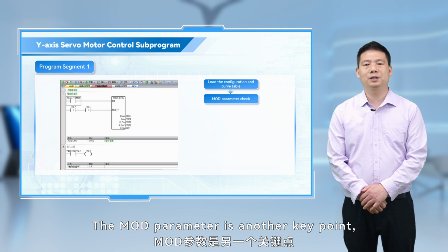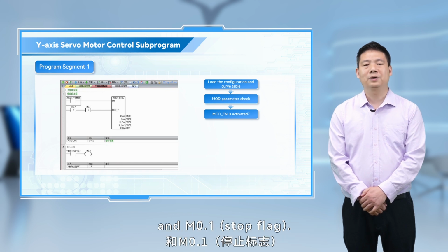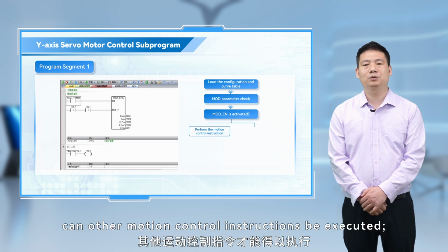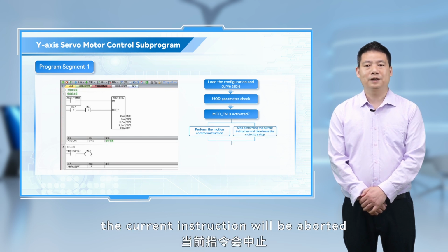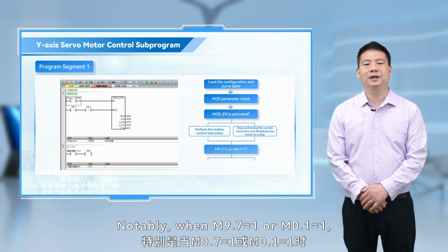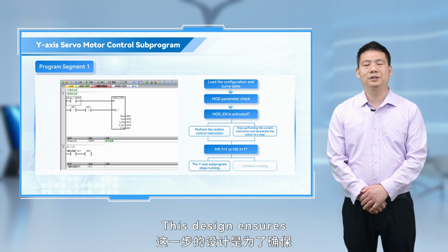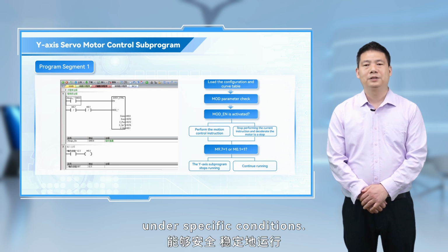The mod parameter is another key point, which includes M9.7, Y-axis home position flag, and M0.1, stop flag. Only when mod EN is enabled can other motion control instructions be executed. Otherwise, if mod EN is disabled, the current instruction will be aborted and the motor will decelerate to a stop. Notably, when M9.7 equals 1 or M0.1 equals 1, the Y-axis subprogram will stop running. This design ensures the equipment can operate safely and steadily under specific conditions.